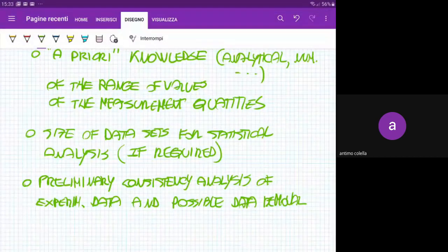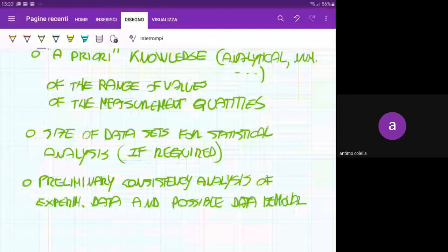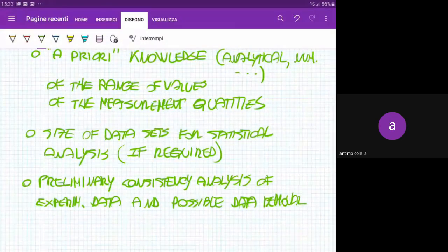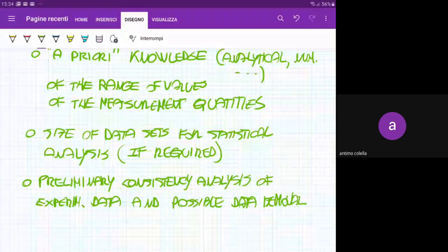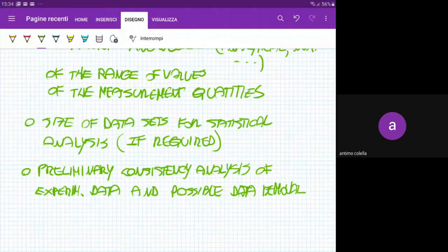measuring chain is working well. Okay, not from the data point of view, but from the measuring chain point of view. Okay, so all the sensitivities are okay, the transducers are the good ones, there are no broken transducers, connections and whatever effects is fully taken into account so that you are having a good measurement. Okay, if not, what happens? Stop the measurement? Not at all, because you are going to be paid for doing that. Therefore, you have to do some action.